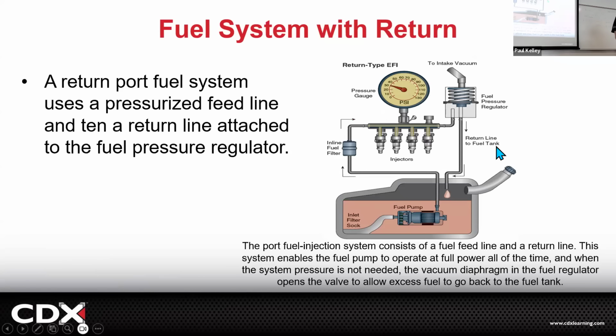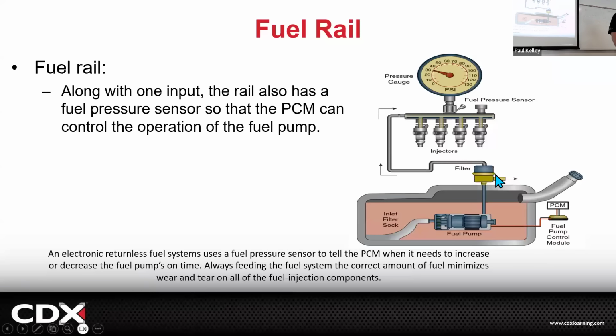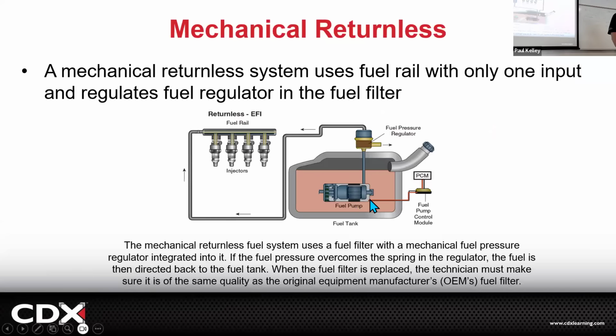And this is just a little bit of review. Remember, it has the vacuum line, and this has a mechanical fuel pressure regulator and the whole return line. That was a good shot of that whole system functioning. This is going to be more current, where it's got the fuel pressure regulator down in the pump.